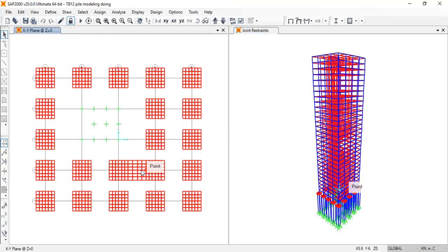For a combined pile, I think the pile is here, and for this area you can have a large combined pile cap and have piles at some locations for the modeling, right? And here, maybe 12 piles can be there. Here also, it's a combined pile cap. So the same thing. You know how to get the capacity of the pile, and there are only a few stability checks to be done, which can be done later.